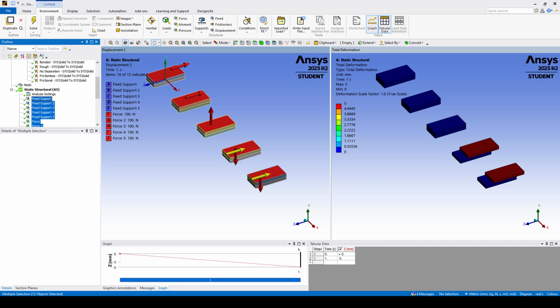Frictionless contact represents a classical unilateral contact behavior where surfaces can separate freely but cannot penetrate each other. So gaps can form naturally depending on the external loads if separation occurs, and normal pressure drops immediately to exactly 0.